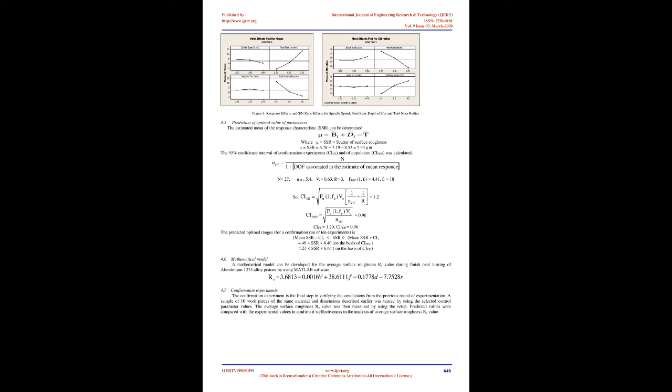4.4 Main effect plots. Feed rate and tool nose radius are shown to have a strong effect on surface roughness and their S/N ratios. The spindle speed and depth of cut had a smaller effect, as evidenced by the shallow slope of the lines. The S/N ratio and Ra effects data plotted in these graphs can be used to determine the optimal set of parameters from this experimental design.